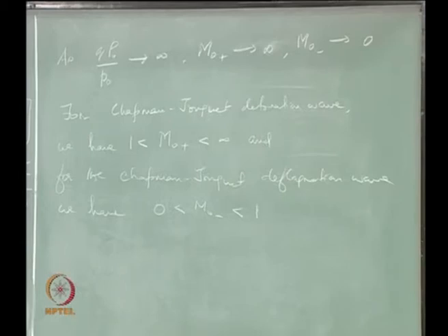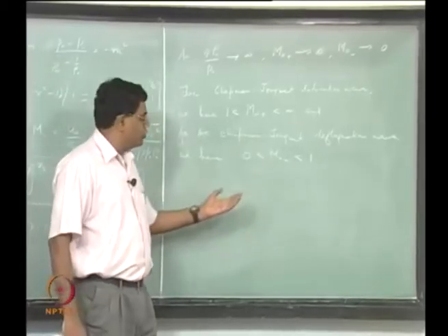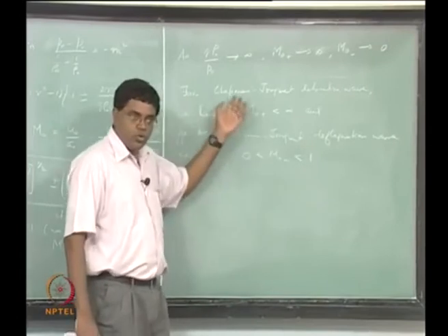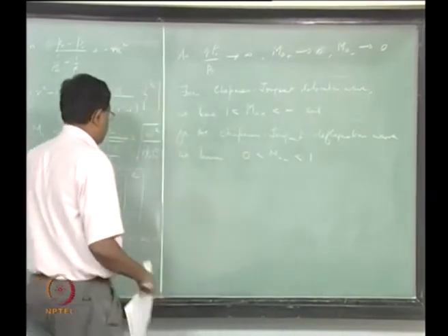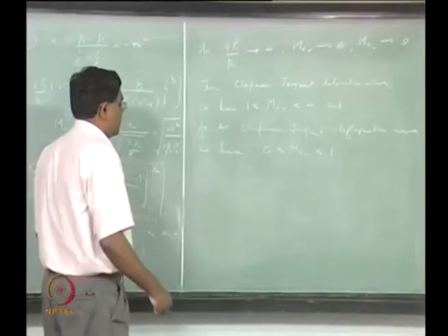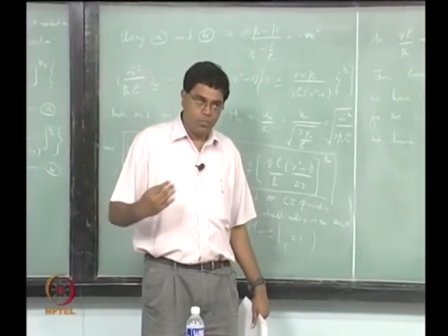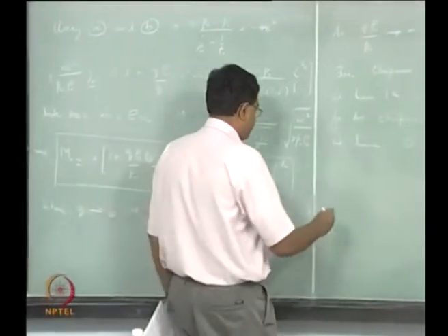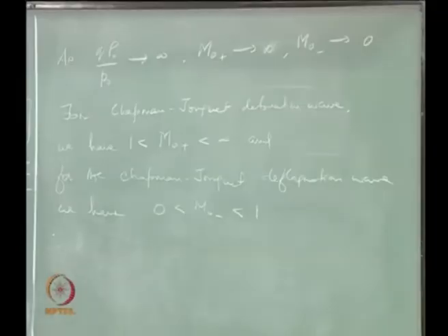and what that means is the M naught is not really going to overlap between these two, okay. So this is going to go only up to 1, that's going to go only above 1, okay. So that means a detonation wave propagates at supersonic speeds, and a deflagration wave propagates at subsonic speeds. Well, let's not just jump to that conclusion yet. There is just one more step that we have already talked about.